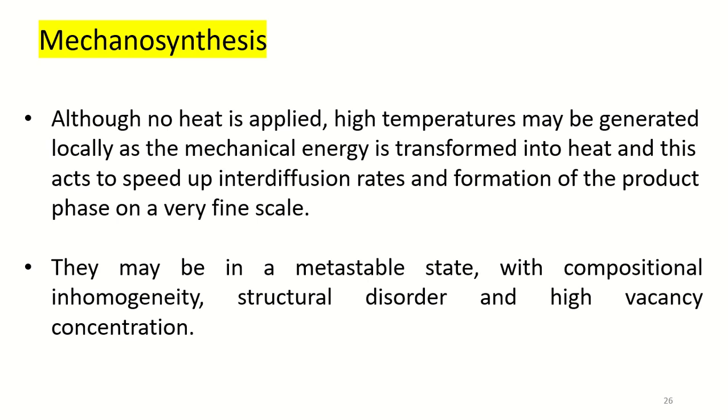The products of mechanosynthesis may be different from those of the same material prepared by solid state reactions. They may be in a metastable state with compositional inhomogeneity, structural disorder, and high vacancy concentration.